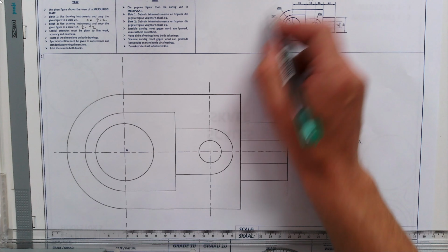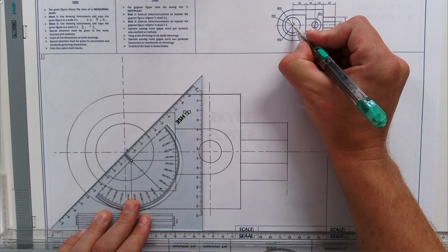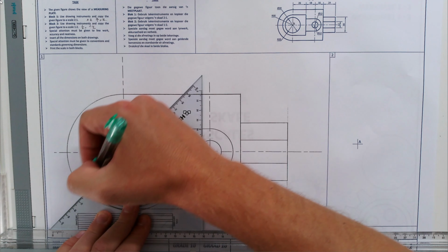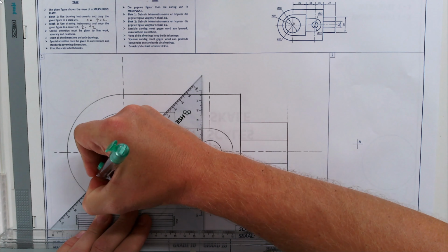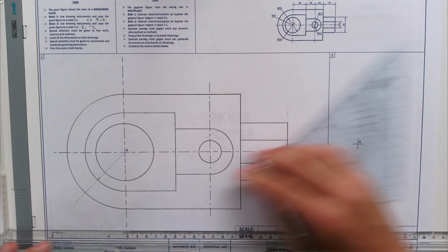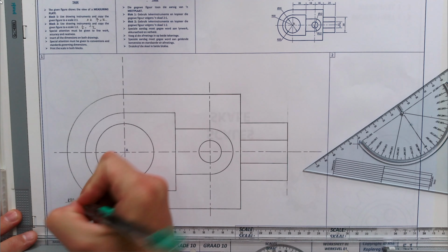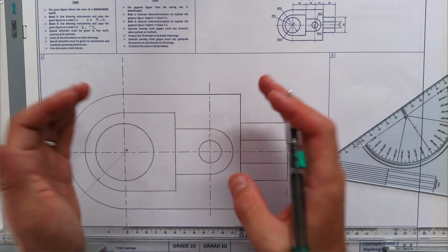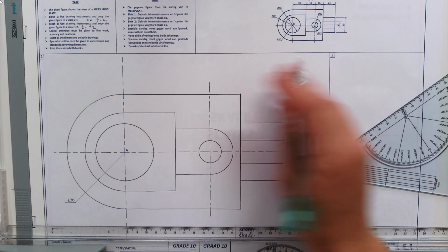So this has a radius of 20. So I'm going to put that radius in there. It's from the middle point to this circle. Light in construction, very light, from the middle. Instead of using an arrow, I'm just darkening the tip over there. So you can see from A to there, that will be on a line, radius 20. I'm still using these dimensions. It is only the drawing that has changed, not the dimensions. I'm not going to say here 40. We keep it its original dimensions.